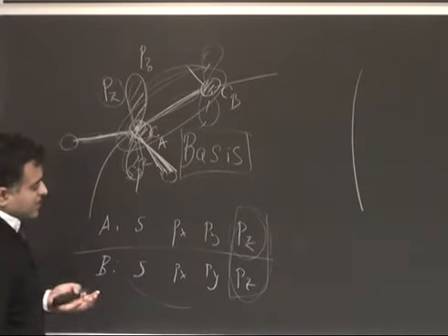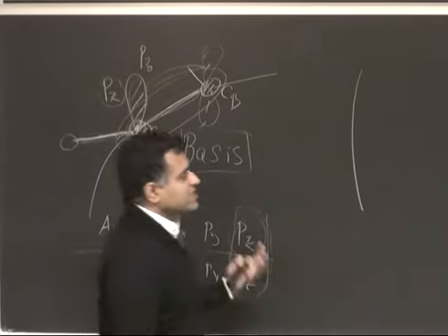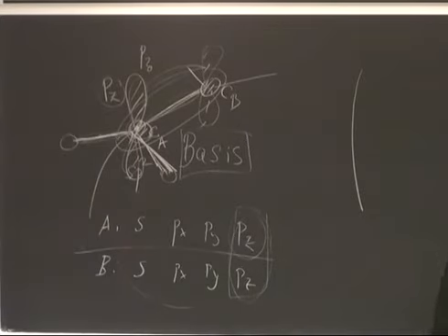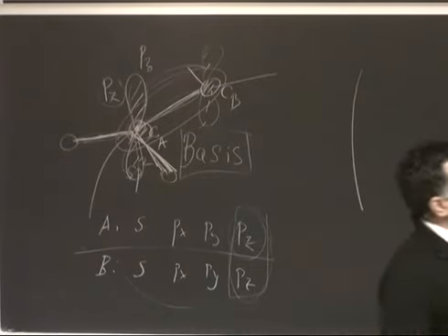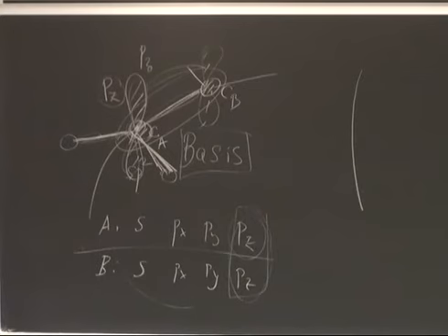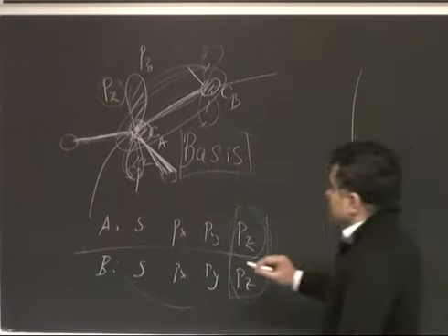So totally there'll be 8 bands. And that also happens to be the minimal set of bands for silicon and gallium arsenide and compound semiconductors, and we're going to see that now. I'm showing here the 8 bands. The solid ones are the ones that are filled with electrons, because the solid has a finite number of electrons.